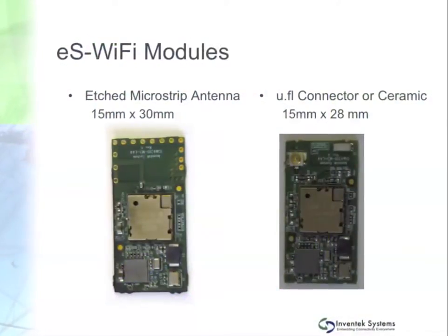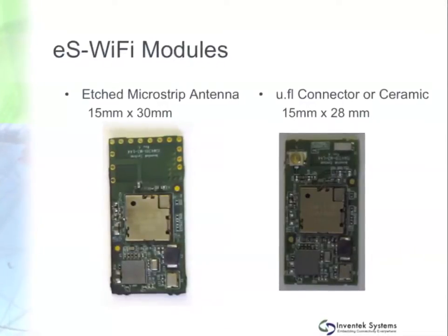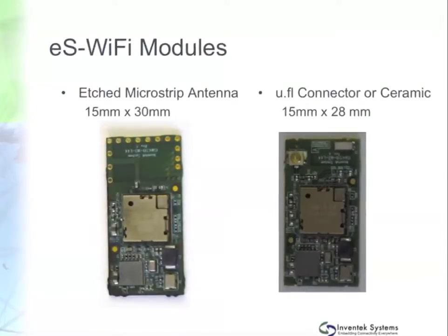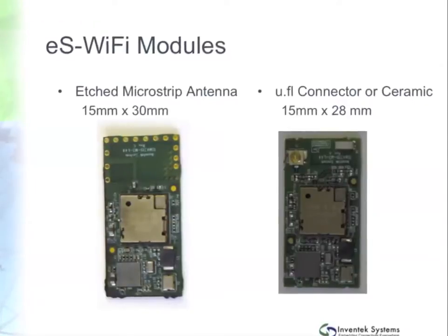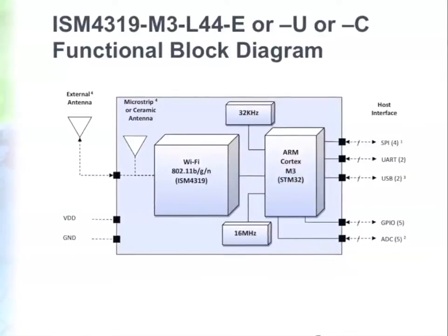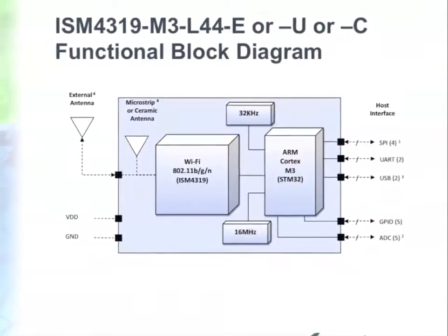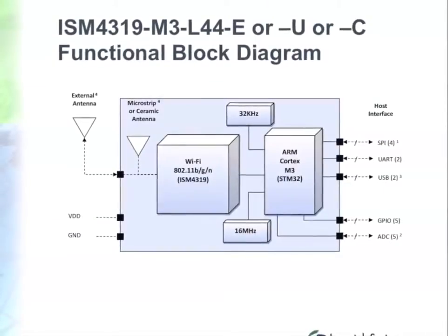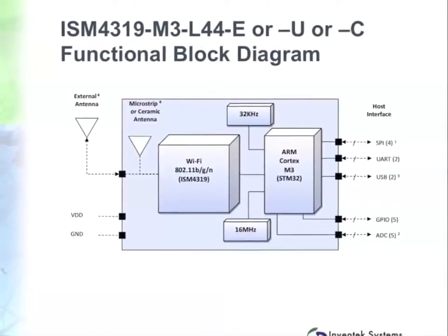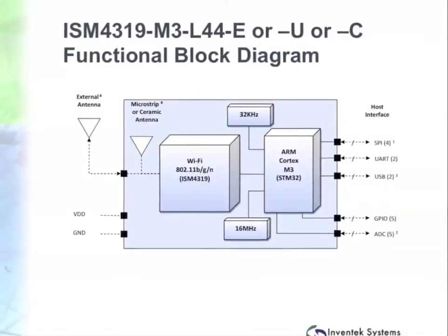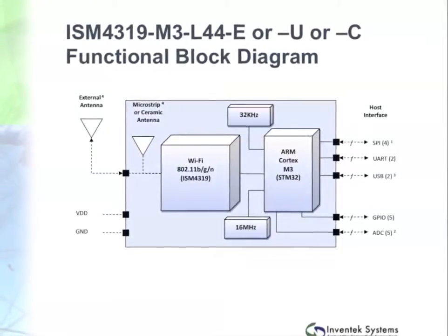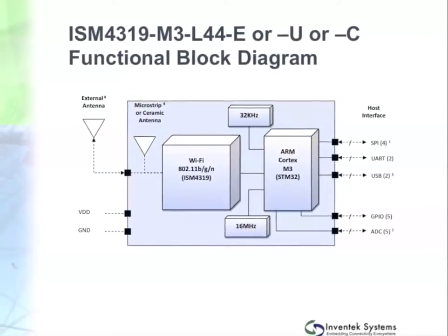The eS-WiFi modules are wireless LAN modules that are typically embedded into devices and appliances that connect to home networks, Wi-Fi hotspots, and workspace networks. The eS-WiFi family of 802.11 BGN modules have an embedded microcontroller running a fully integrated TCP/IP stack and a simple-to-use AT command set. The eS-WiFi modules are based on Broadcom's Wi-Fi technology.